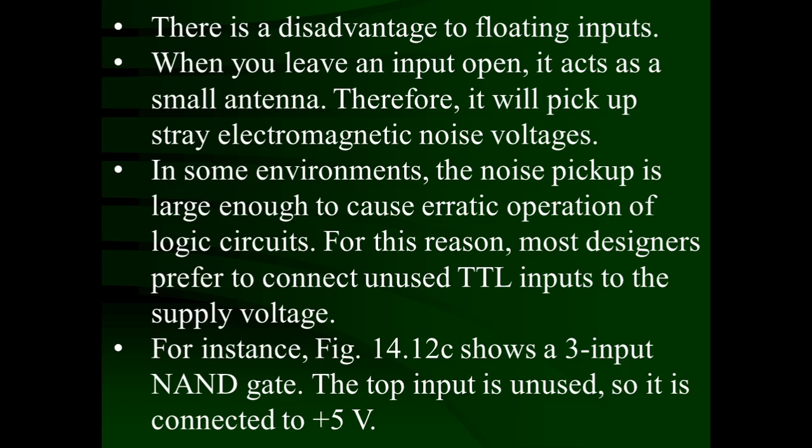So this has to be prevented, and to prevent this one, the unused input is normally not advised to be left unconnected or floating, but it should be connected to either VCC or ground. Just I am reading the same thing over the PPT. There is a disadvantage of floating inputs. When you leave an input open, it acts as small antenna. Therefore, it will pick up a stray electromagnetic noise voltages. In some environments, the noise pickup is large enough to cause erratic operation of the logic circuits.